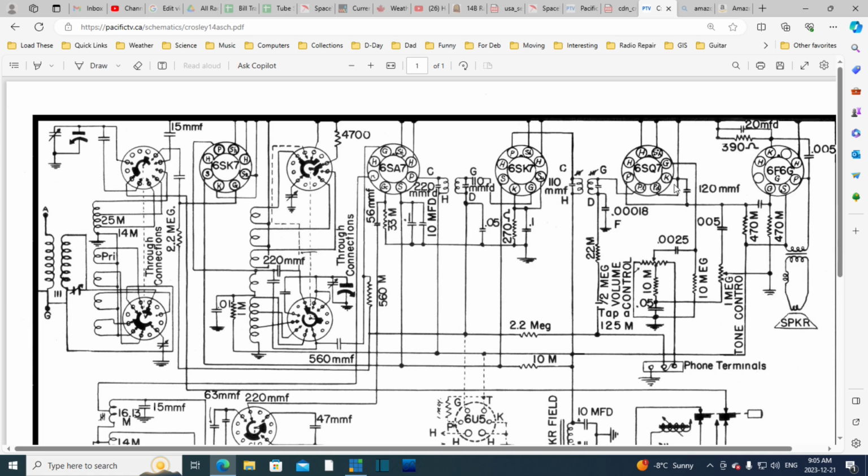Now here's the thing, I've got to do a little research here, but I think there's only one cathode in this tube. And the one cathode is providing the electrons for both functions. Well, wouldn't it be the case that if you draw off electrons from the cathode, you don't actually draw them right off the cathode, you draw them off a pressurized field of electrons just on the surface or just outside of the cathode, but if you were to draw that down, surely that has an impact on the current flow through the tube, out the plate, and over to the grid here.